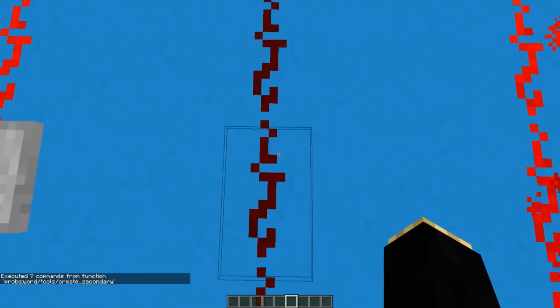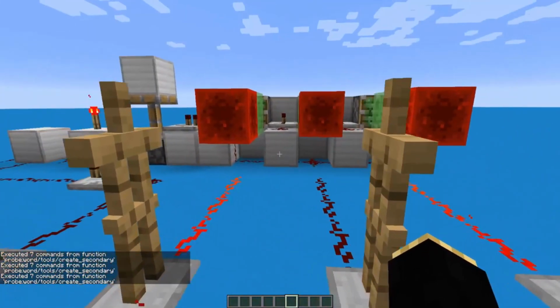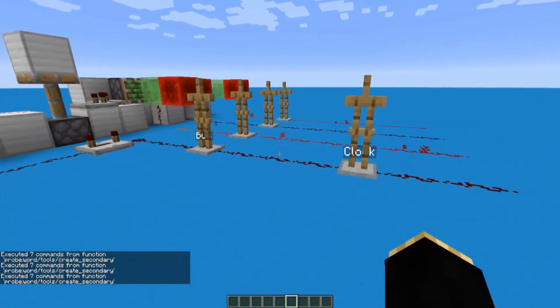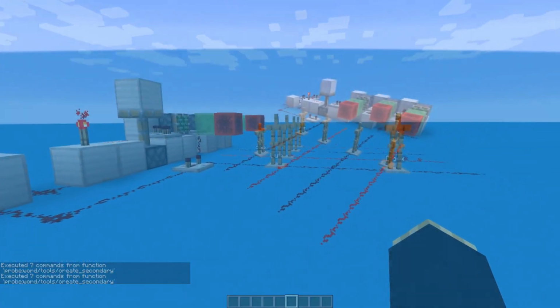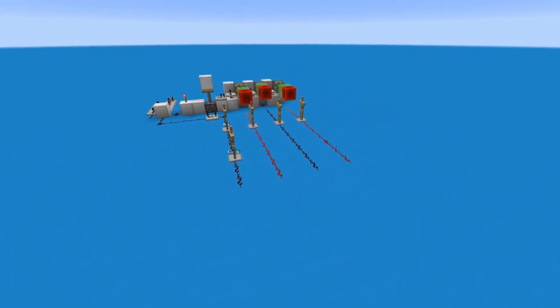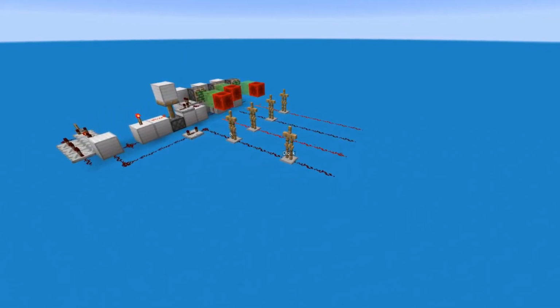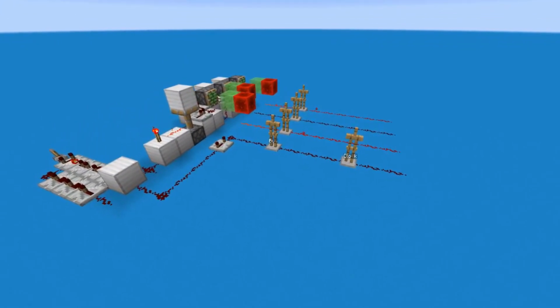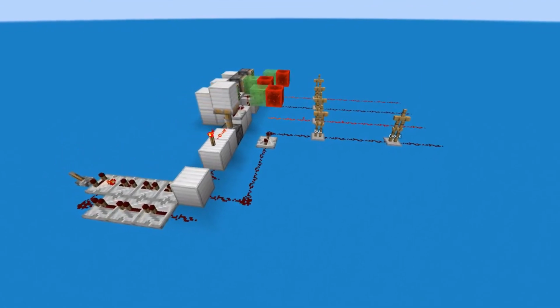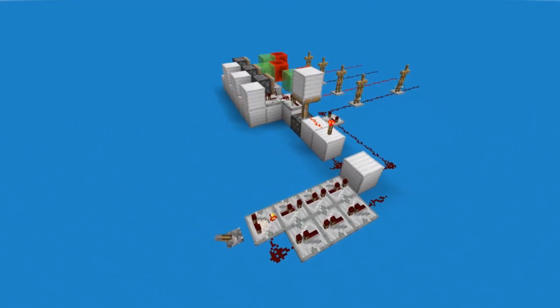You're then going to repeat these steps for the remaining bits in your word. It's important that you start with the least significant bit and work your way up to the most significant bit and operate in that order. And it's also important that you don't exceed 32 probes. If the bus you're trying to measure has more than 32 bits, well, that might be a problem. At this point, my data pack nor my program actually supports any integers that big. It may be something that I'll try to support in future versions, but for now, just leave the probe size at 32 bits or less.